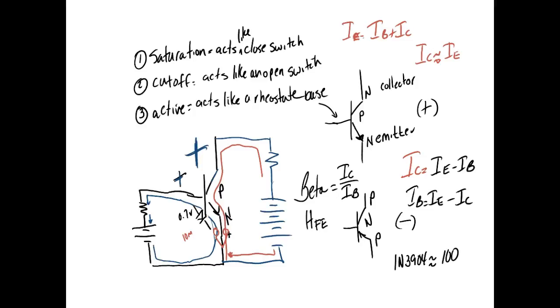We'll measure the base current, the collector current, and the emitter current. And what I'll do is I'll make this resistor right here adjustable. If I make that adjustable, then what does that mean? I can adjust the amount of current. This resistor right here will drop whatever. This guy right here is actually setting the current, right? You'll understand that.